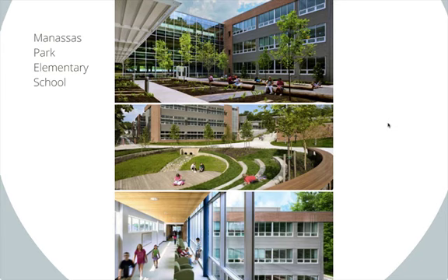Acoustical comfort was addressed by minimizing sound transmission between rooms using appropriate detailing and material densities, as well as acoustically absorbent materials used on the ceilings to lower the reflection of noise levels. And finally, air quality was addressed with a heat recovery ventilation system, which introduces fresh air into the building but also maintains climate control and improves energy efficiency. It's like being able to open the windows without letting in the heat or the moisture.